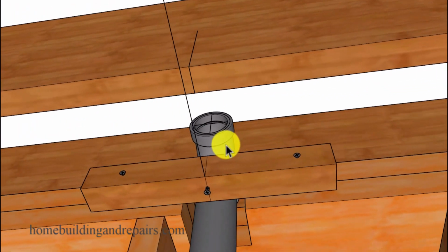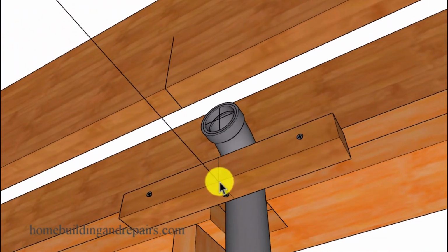So in this example here, I'm just kind of giving you an idea of what we need to measure and what we're going to do with those measurements. I need to measure from the bottom of this board to the center of the fitting. And if this block is level, which it should be, you should be able to measure from the little tab or the mark that represents the center of the fitting on the outside of the fitting. So I could just simply measure from the tab here straight down, or measure from the top or the bottom and then calculate the center. And in our example here, this just so happens to be exactly 5 inches. And no, I did not plan that, but it does work out every once in a while.